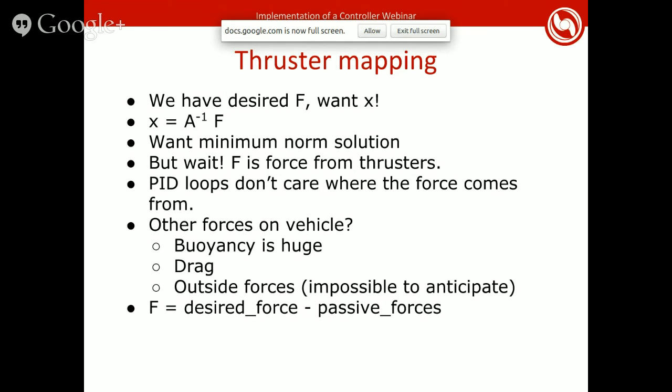So a smarter thing to do is have the controller be aware of these passive forces. Then the controller will be like, okay, the PID loop, you want a torque, an angular acceleration, that's going to roll you back. Well, look, buoyancy is already providing that acceleration. So I'm not going to do anything. Let the gravity bring the vehicle down. If you have oscillation problems, this will fix them, if this is the cause, of course. This was a problem with us, and we added this model. We added this passive forces abstraction, and we stopped oscillating, which is great.